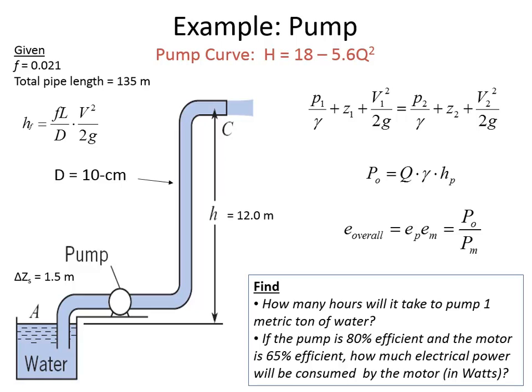You just worry about the length of the suction side. Cavitation. When you're doing the NPSH problem is when you're focusing only on the suction side. Good question, because last time we were looking only at the delta Zs. And so this figure could be used also for a cavitation problem, which is why they separately called out what the suction side length elevation difference was. Was there another question?